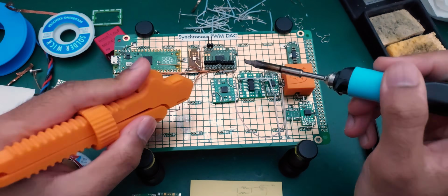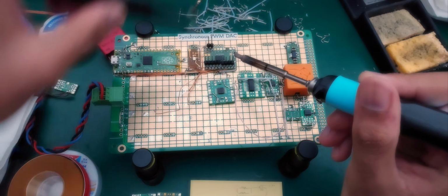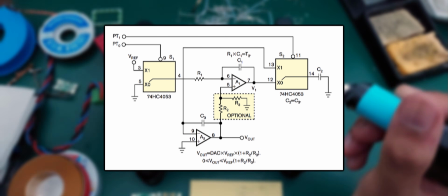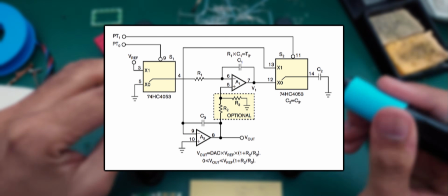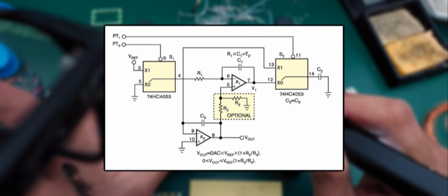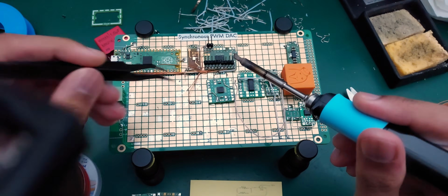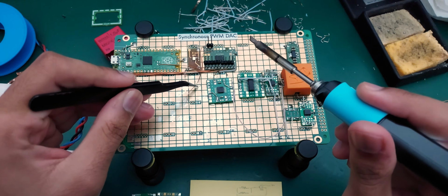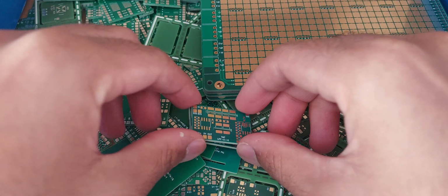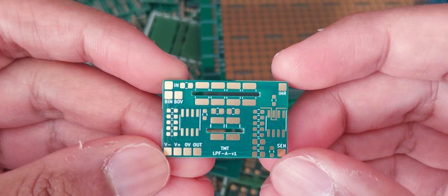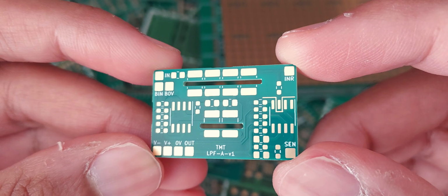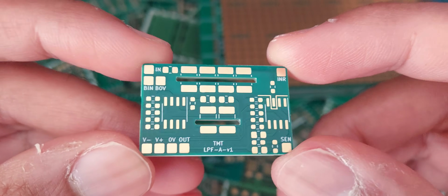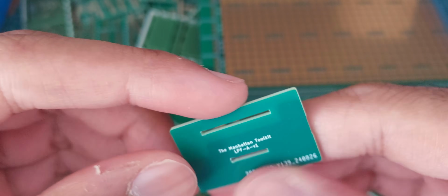It's time for another rebuild of the PWM DAC. Synchronous filtering, which I investigated in the last video, failed to live up to the expectations of low ripple and fast settling, which were complicated by the dynamics of switch systems and imperfect component matching. At the end of the last video, I hinted at using these mysterious PCBs, which take a step back from synchronous filtering to active filtering, which forms the premise for this video.